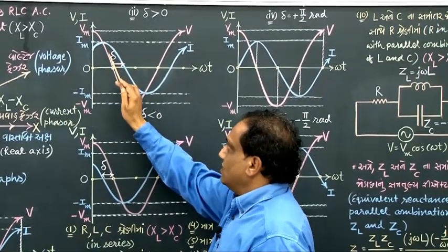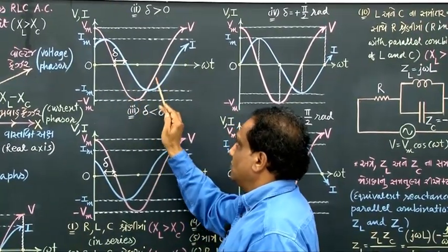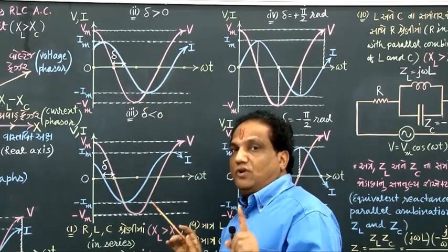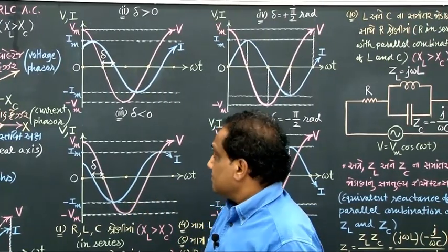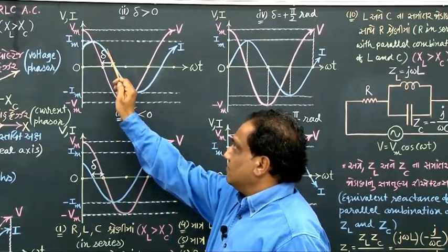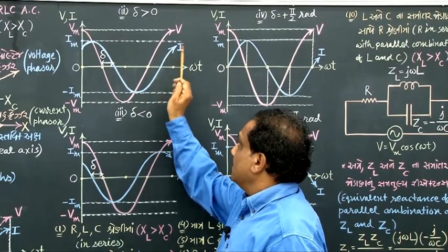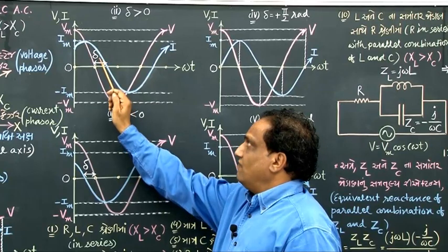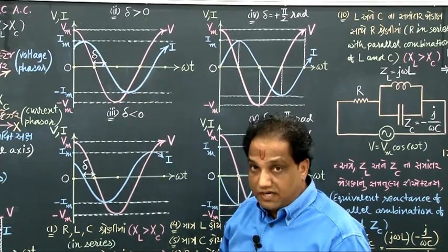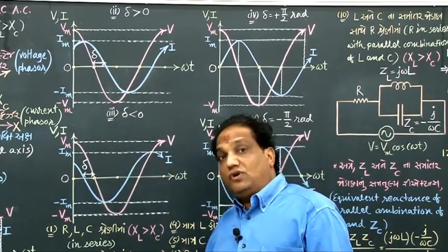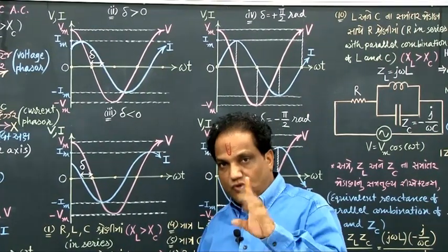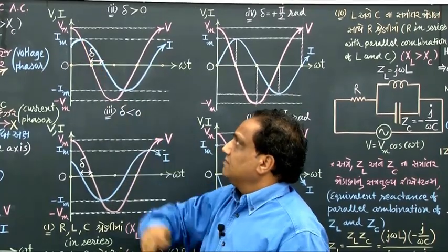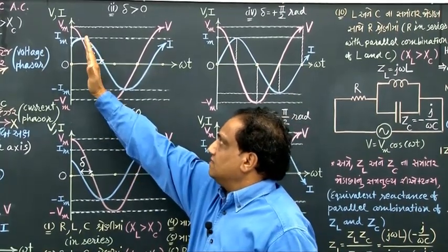And then after it goes on decreasing, again goes on increasing, again goes on decreasing, again goes on increasing. That is how it changes periodically according to the cos function, fine. The current graph is this, shown with the blue color, okay. Then here, this much angle gives you the phase difference between voltage and current. How can we say that voltage is leading in phase? I am showing you. You start with their maxima, and move towards the right hand side this way, correct?